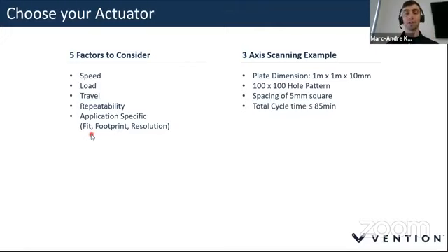And as we will see later, we have also options to micro step the stepper motors or use a gearbox to change that resolution depending on your choices. So here it could be all sorts of factors that could help you very specifically for what you want to do, help you narrow down your choices.